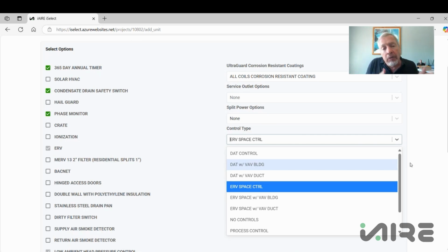They call it a cooling mode, and then they call it a dehume mode. Technically, our units are always in the dehume mode. So I'm going to say this again. We always control the discharge air temperature. Now, why then do we have a control type called discharge air control, or DAT, as you see it here? Because we can control a unit to the discharge air temperature.